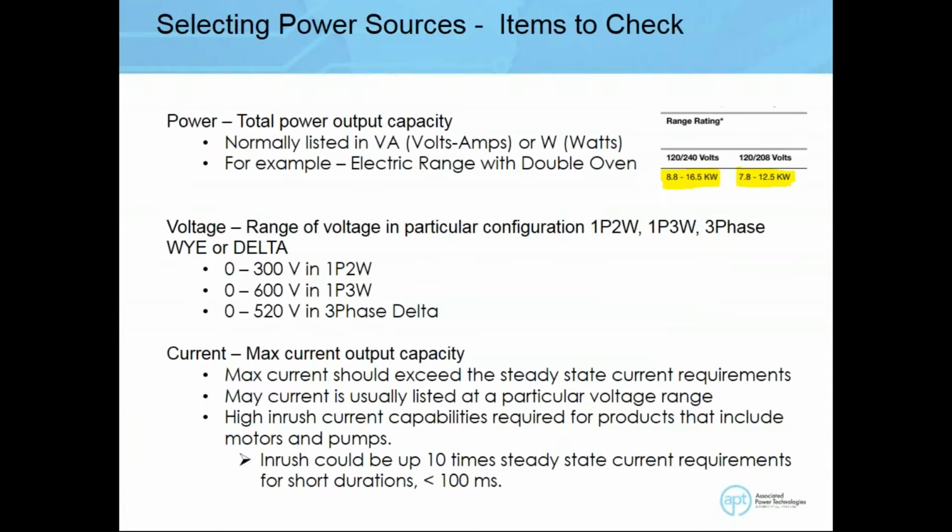All right, so since we learned about having these different types of power supplies, what would you need to check for when you're sourcing out a power supply? Now, the first thing that I would look for is the power output. If I have a product that needs to power up, I need to be sure that this power supply is able to sufficiently meet the power requirements.